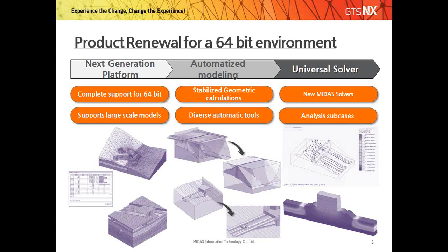GTS NX will be a new generation platform. It will be a completely supportive system for 64-bit software, and it can support very large scale models, which I will be showing you in the upcoming slides. With autonomized modeling, it has stabilized geometric calculation and diverse automatic tools, and it has a universal solver. As you all know, till now MIDAS GTS was in collaboration with TNO for its solver. The post and pre-processor were with MIDAS and the solver was with TNO, but now with GTS NX we are going to have our own solver.